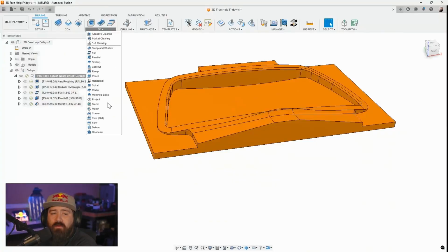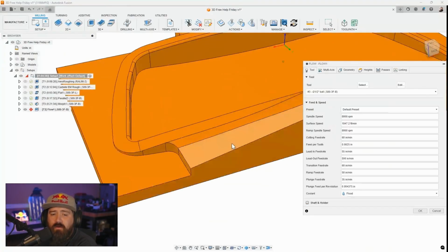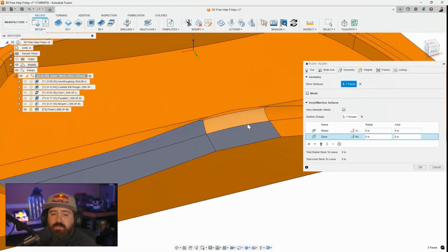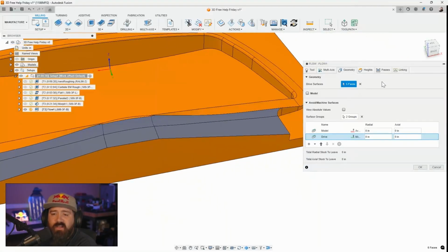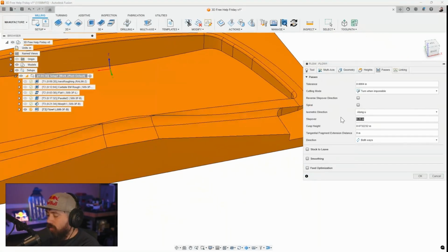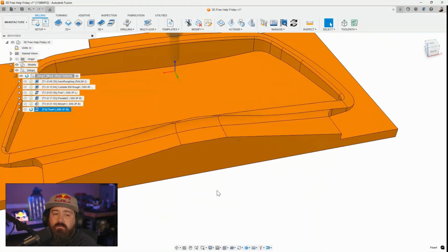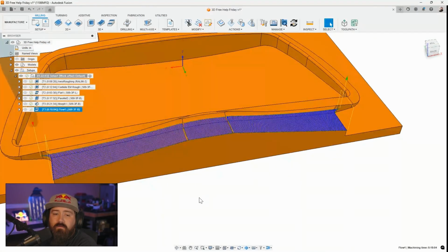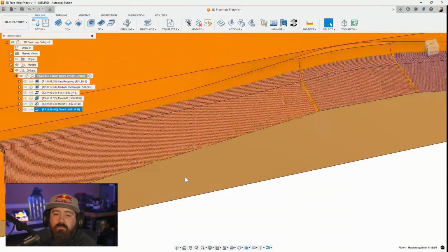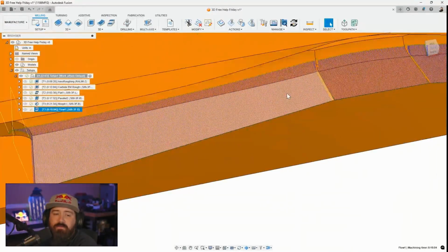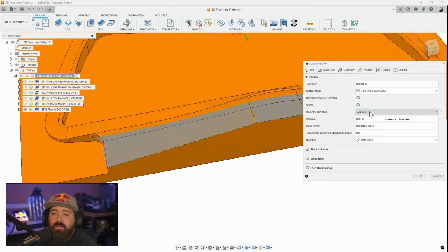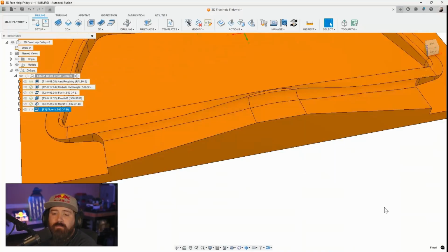Another one that would be great, probably easy to do, would be flow. If all of these match up or this makes a nice toolpath, we can just hit on there, tell it what step over we want, and hit OK. It should do that almost right away. The pattern goes the other way, so we can try to reverse it so we can get it to blend together. Say a long V.